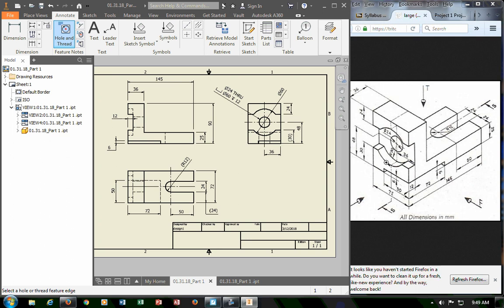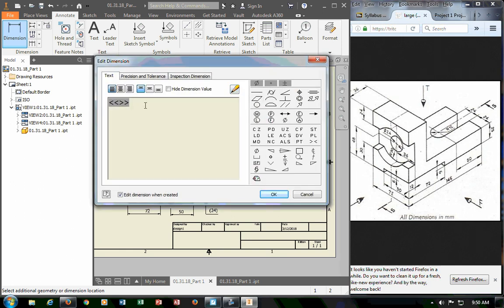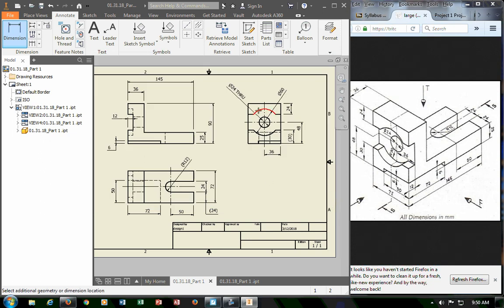Well, it shows here as a radius of 30. If we were going to do it the other way, you'd actually have to drop an actual dimension in. Diameter 24. And then you would add to the end of it through. And then this will come out as a radius. I would probably put it at the bottom though, because it's got enough clutter at the top. Something like that.